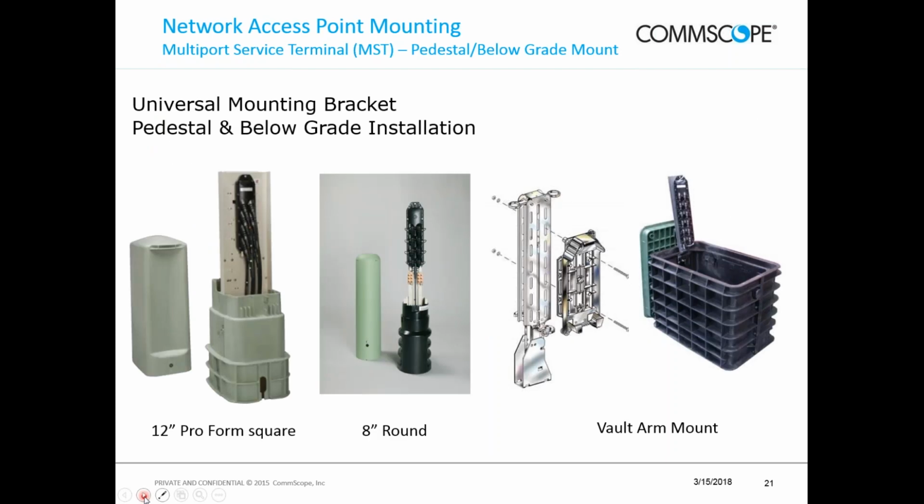Just a slide here on how MSTs are typically mounted, at least in pedestal and below grade. Just a couple of examples here. It's a typical 12-inch square ped, 8-inch round. They'll fit in just fine. Any type of vault with an arm mount is obviously much better. As I said, these are environmentally hardened, so if this MST is just sitting in the vault, that's fine. As long as the hardened connectors were installed correctly and tightened down correctly, it's not going to leak. Even if it's under 3 or 4 feet of water, it's going to be fine. But make sure that all those ports are closed off and correctly tightened.